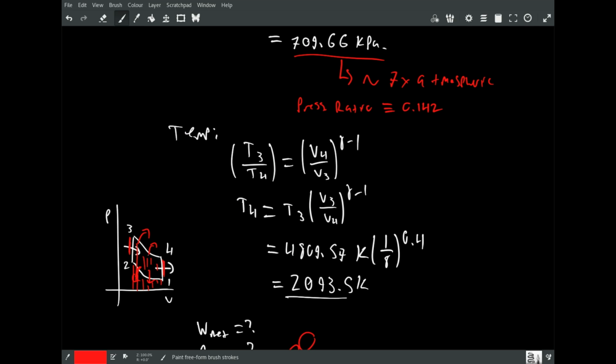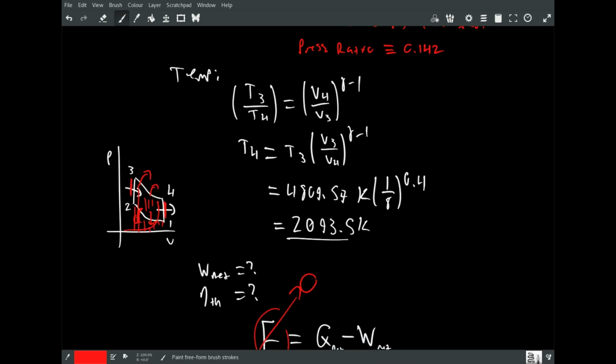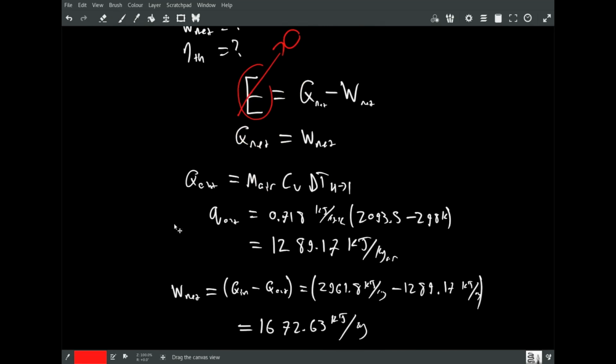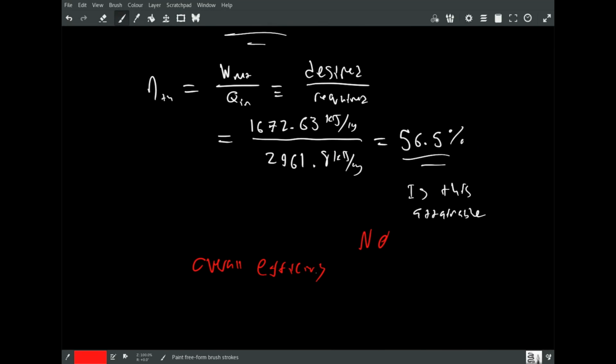We're going to have a non-constant volume heat rejection, because when we are exhausting, it's not going to be constant volume, it's going out. And in addition to that, we're going to have pumping losses because we have to pump the air into the cylinder. So in reality, our overall efficiency is going to be less.